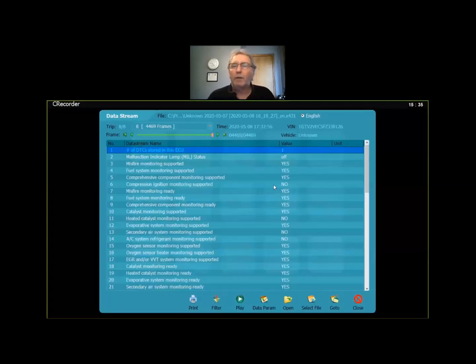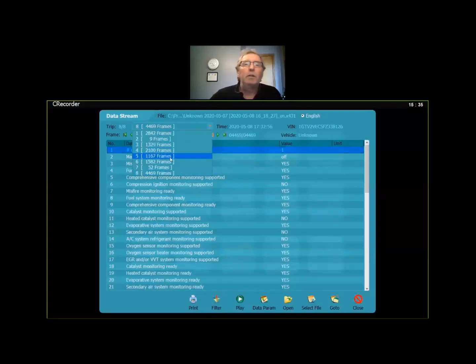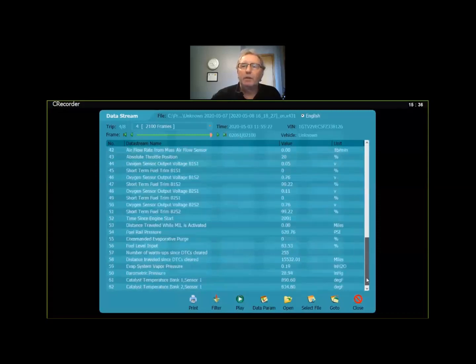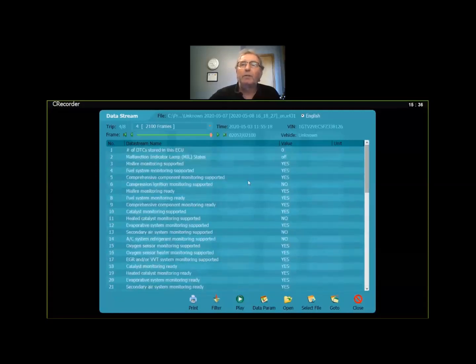But this lecture and lab hopefully fit together really well. When I talk about the Evap monitor, you saw it in action, right? We saw in trip 4 here at frame 2060, we started, everything was fine. When we hit frame 2060, we set a code, and then the light came on in frame 2061. During that time, the vapor pressure never got up to that -16 that we saw when the monitor ran and passed. And then we go to trip 8 where the light went off, and that was somewhere around 826 was the frame here.